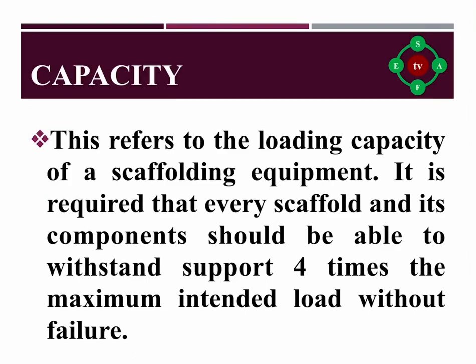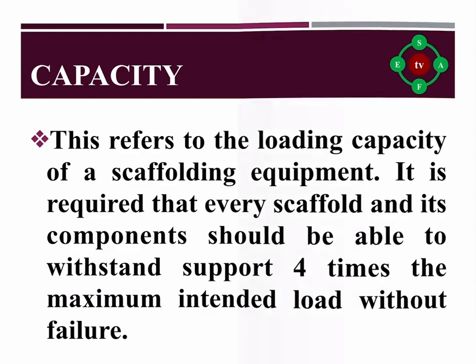Capacity. This refers to the loading capacity of scaffolding equipment. It is required that every scaffold and its component should be able to support 4 times the maximum intended load without failure.